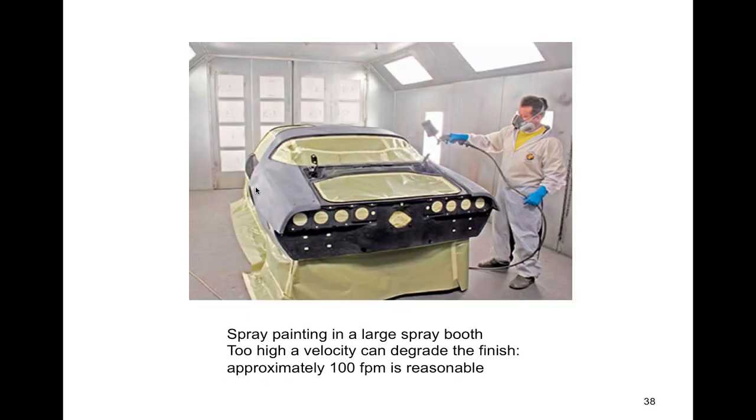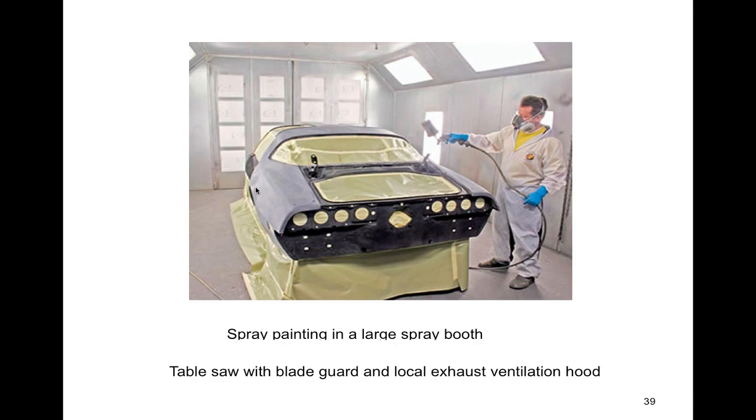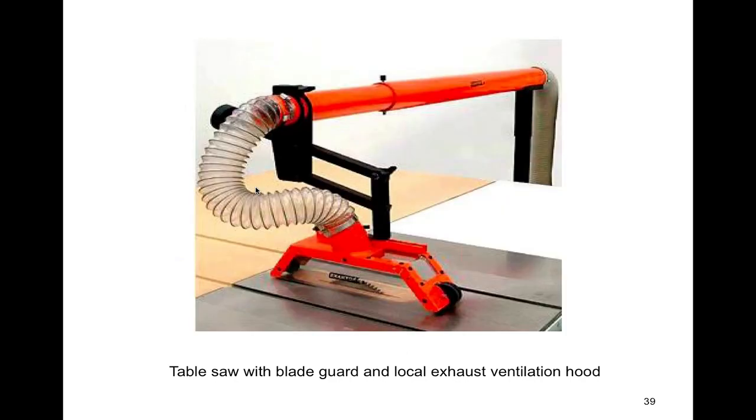Okay, spray painting booth. Yes, you have a spray painting booth here. That whole wall against the back there is basically a suction hood, and those filters capture the paint dust, so it doesn't get pulled into the system. Now, notice he's on one side of the car. If you stand on the other side of the car, you're going to get blasted with this stuff.